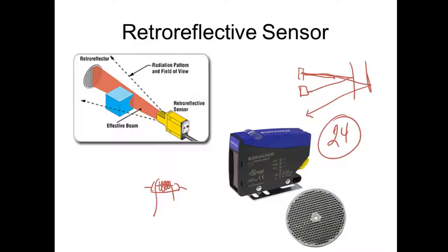You get out at an older company like U.S. Steel, you're going to run into a lot of 120 volt stuff. Well, I'm talking about the control circuit. 240 for power, but the control circuit, the relays are usually 120 volts. So when we bought our trainers, that's what was available. So that's ours, 120 volt trainers over there. But the sensors that we're going to use, some of them are going to be 24 volt, but they're going to have relay outputs, which means they'll be able to control a 120 volt circuit. Does that make sense?